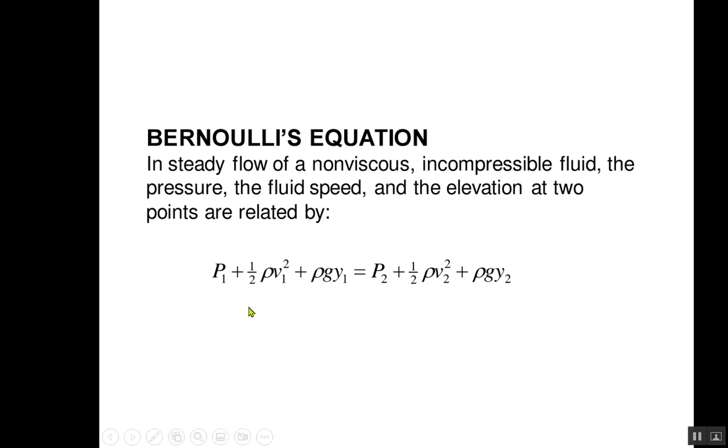Now remember, what we have here is an energy density, some existing energy density. Remember rho g y, where y is your y coordinate, or h. You could have called this height before. The height difference is a potential energy term. So we have the potential energy term at point 1, and we're comparing that to the potential energy at point 2, some scalar that exists there on the gauge, and then 1/2 rho v squared.